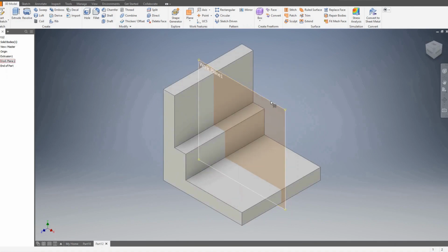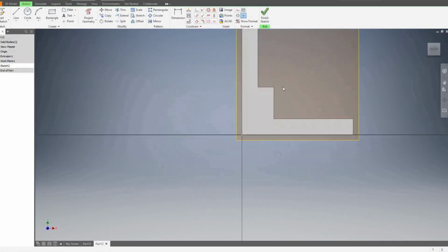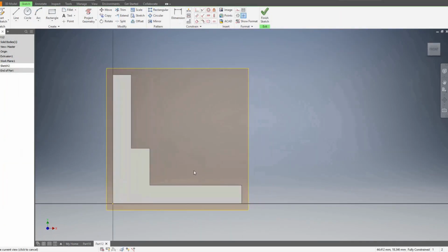I will left click on the plane, select Create Sketch, reposition my sketch holding in the middle button, select Project Geometry onto this plane. Please note you have to do this before adding your points and your lines, not after.